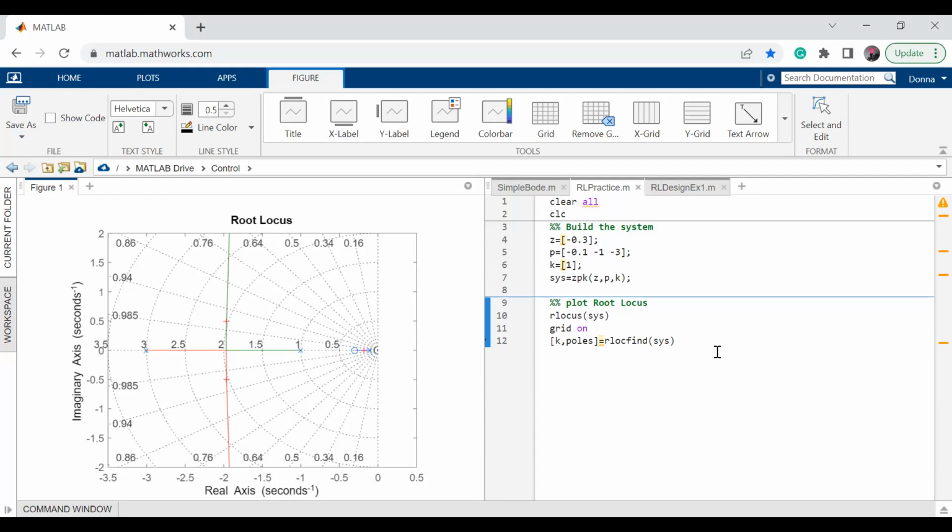Yes. Because s is j omega, right? So you're looking for that frequency. Good job. It also means the other way around. If your system has poles at -1, -2, what does it mean? At those specific frequencies, my system behaves in specific ways. So s, pole, zero, they don't mean anything in a physical sense. That's why they are the bridge between the two domains that we understand but that are so far apart. To connect them, or see them at the same time, someone introduced the s domain: let's talk about them together, and then we can always convert them.